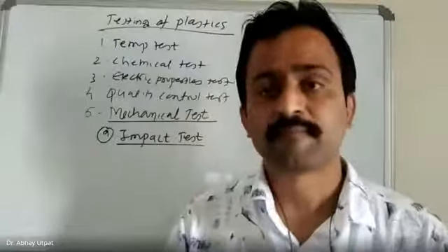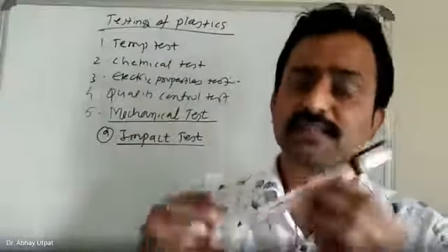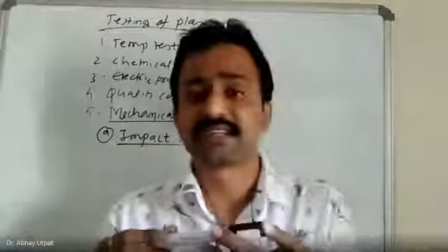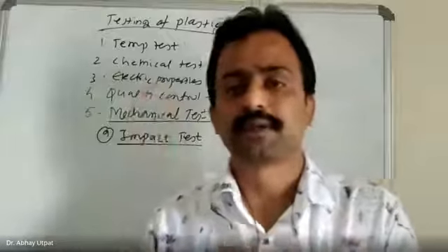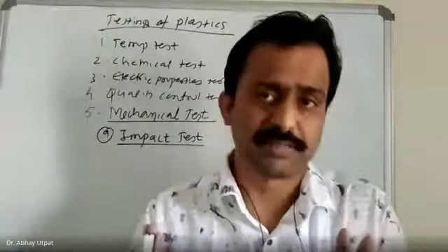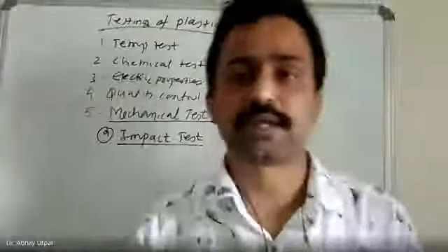So the impact test applies to a plastic component fitted in some mechanism where there are certain chances of impact on it. If, due to this impact, it would break into pieces, that test is carried out using the Charpy and Izod test setup.